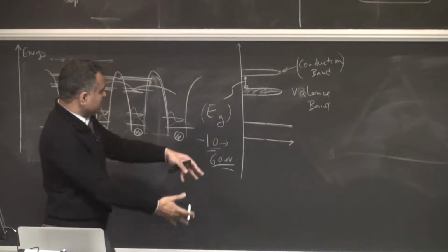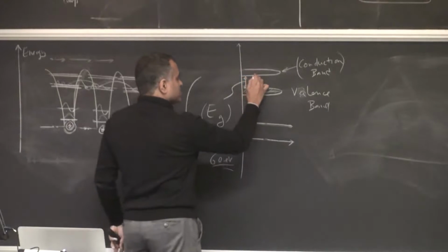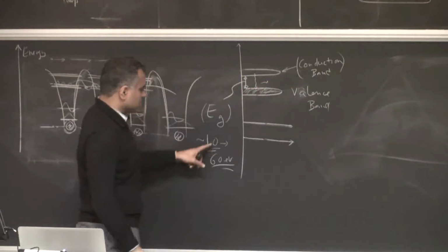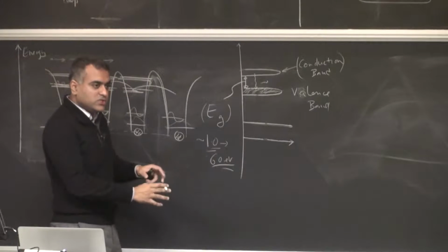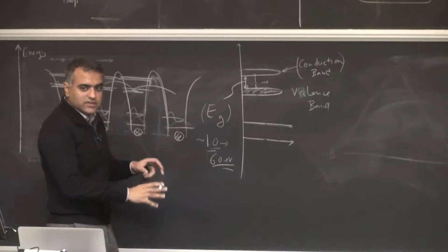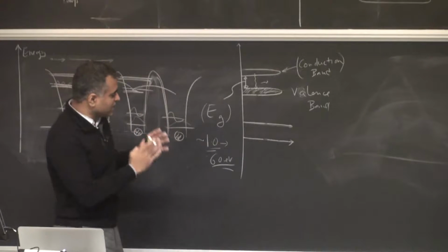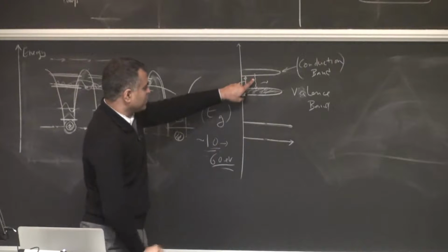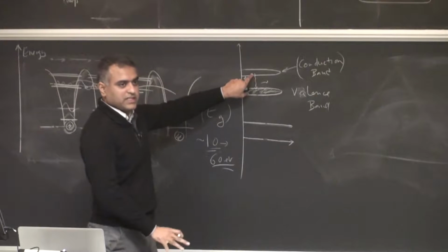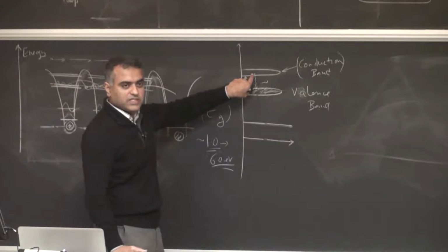And we are going to ultimately look at a transition from here to here. So you can make lasers with all these frequencies now, all these energies now, using semiconductors by choosing different atoms, different materials. You can choose which one you want. You want a green laser, choose your 2.4 or 2.5 eV, choose which atoms will give you that, put those atoms into a crystal and make the laser. That's how the deal with semiconductors is.